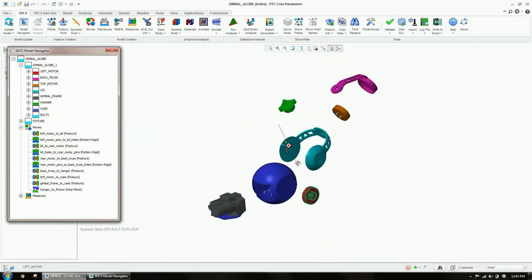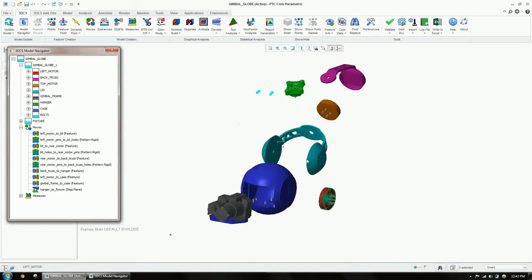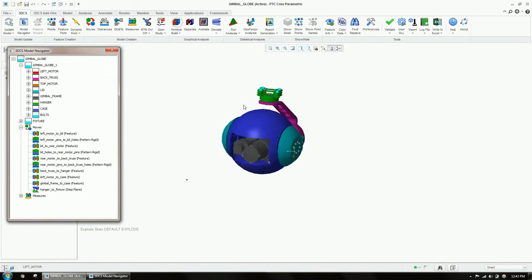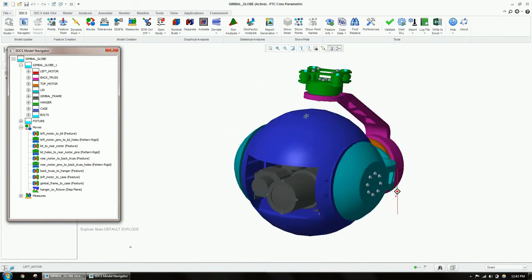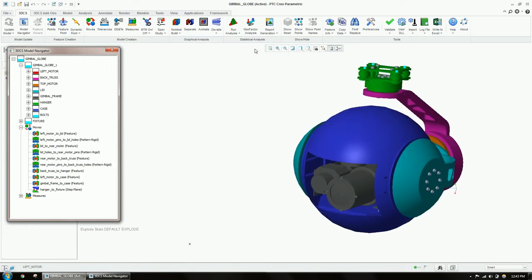Once the tolerances are applied, when I nominal build and press deviate, we can see how the tolerances alter the mesh, which results in the assembly shifting to fit the new constraints. Each deviation is generated randomly within the specified tolerance range. I can also use the sweep button to show a general range of the deviations, which is best seen at the extended point coming from the lens.